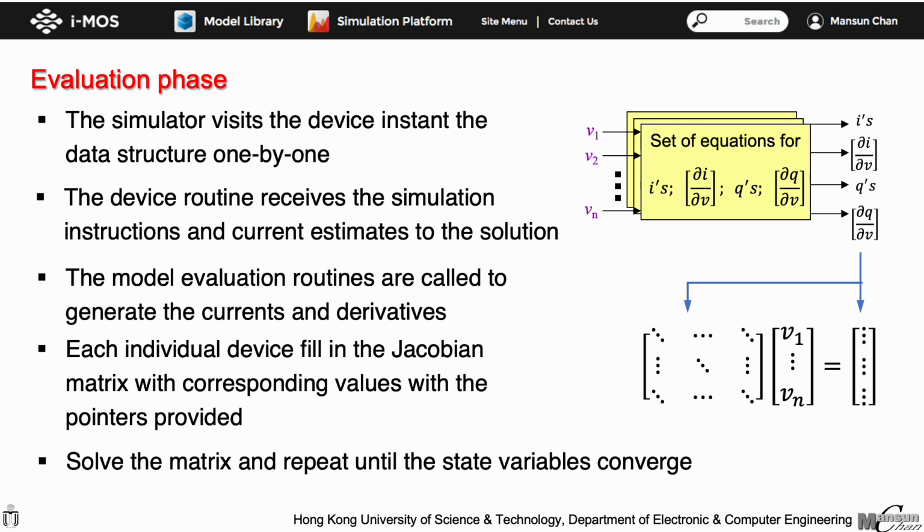Then, the simulator will solve the linear matrix equations to find the next estimates to the solution. The process continues until all state variables converge to some deterministic values. This indicates one solution point is solved.